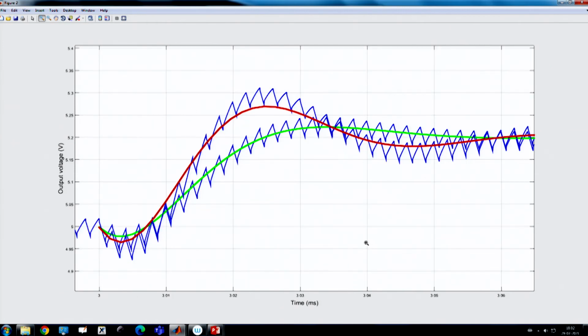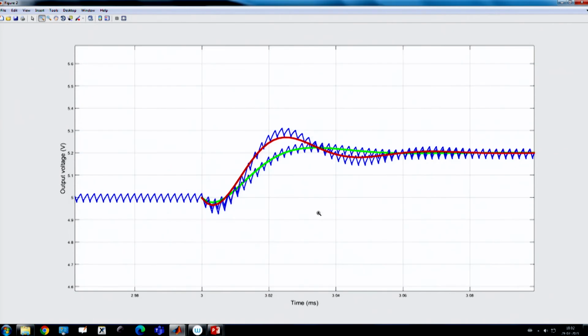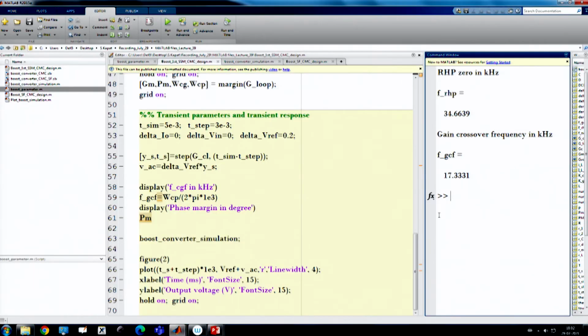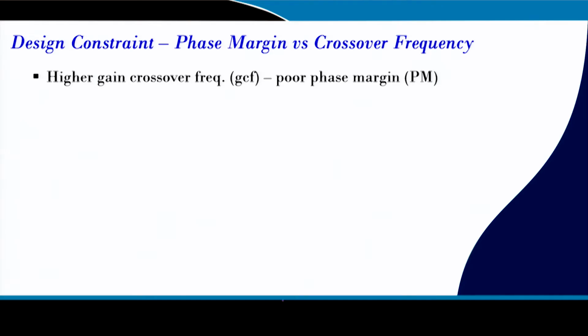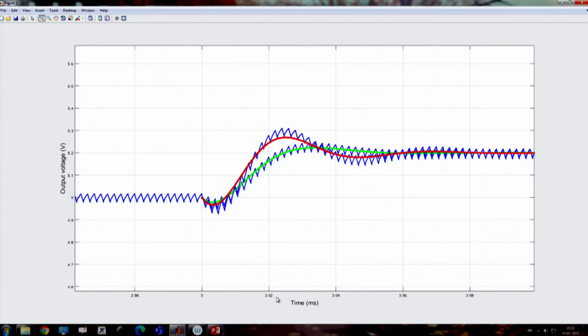Secondly, since the phase margin is poor, because in the earlier design we saw 53 degree phase margin, here the phase margin is 37.5, which has reduced significantly, and lower phase margin will lead to higher overshoot. The phase margin is in some sense proportional to the damping ratio, so poor phase margin means you have a smaller damping ratio.